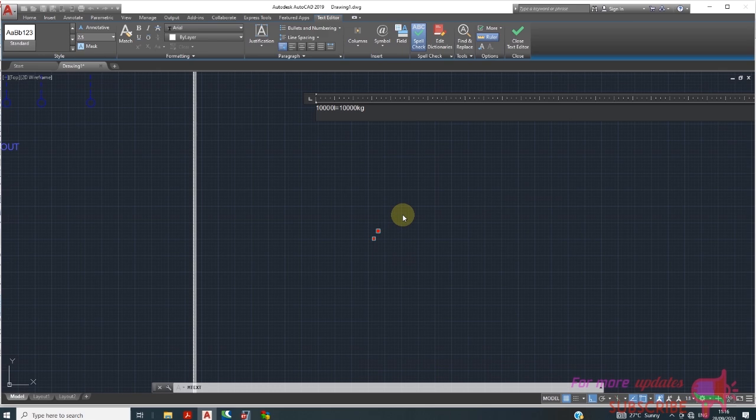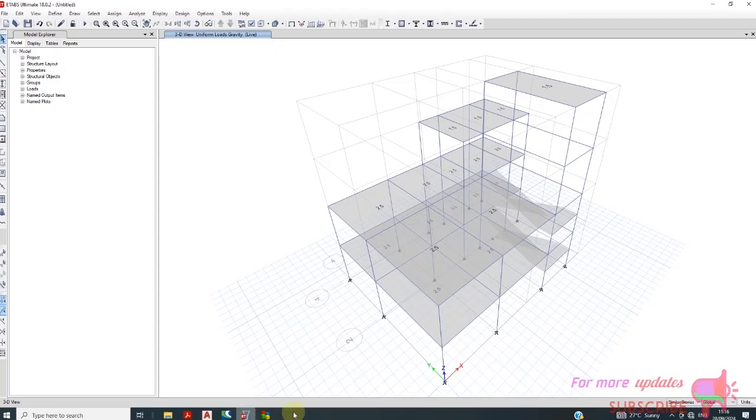You find that each water tank has a load of 100 kilonewtons. Now the uniform distributed load, so there are three, it means 300 kilonewtons. The uniform distributed load will be this divided by the area, that is divided by 5.6 multiplied by 3.72, which is about 14 kilonewton per meter squared.